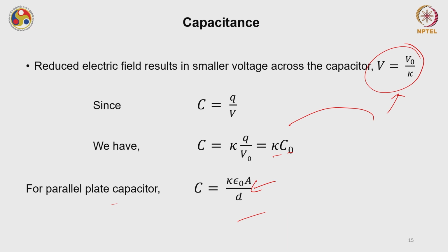Usually you will find that for sensing applications, most of the time there will be some polymer or some other insulator very specific to that kind of sensor placed in between two parallel plates, and rarely do we use air, because it provides better control for sensing applications. So the capacitance between two objects can be defined through a geometry factor G.